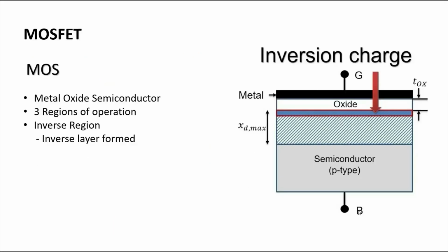We are continuing with the transistors. BJT has been explained by Lokesh, so we can move to the MOSFETs. What is a MOSFET? Before asking this question, we have to study about MOS. Just assume a capacitor in which the two conducting plates are replaced by a metal and a semiconductor. In between there is an oxide, most commonly silicon dioxide, which acts as a dielectric medium.